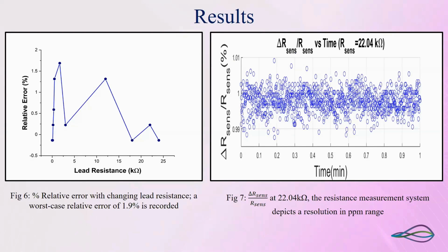But in our next experiment, we brought down the resistance value to 200 ohms. But at that time, we increased the gain by 5 by connecting a resistor between the gain pins of the INA. In that case, we got a measurement range of 200 ohms to 1.2 kilo ohms. But the lead wire resistance was only compensated for 10 ohms to 120 ohms in that case.